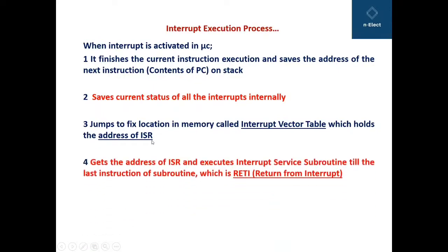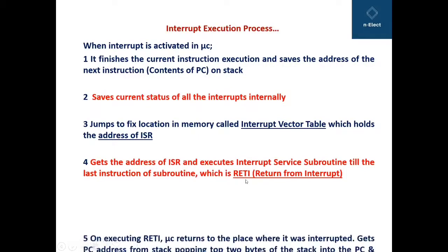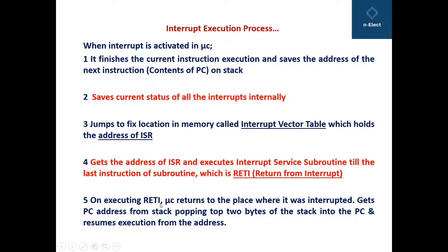It's a program. It gets the address of ISR, that is interrupt service routine, and executes the interrupt service subroutine till the last instruction, and the last instruction of the interrupt service subroutine is RETI, that is return from interrupt. On executing RETI, the microcontroller returns to the place where it was interrupted, gets the program counter address from the stack, popping the top 2 bytes or taking out the top 2 bytes of the stack into the PC, that is program counter register, and resumes execution from that address.